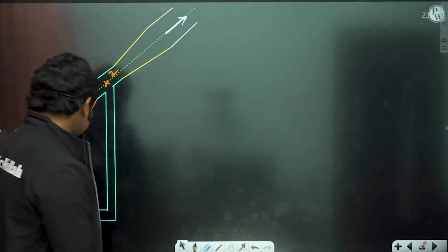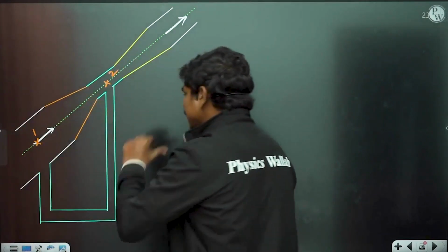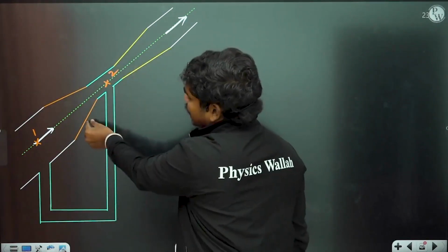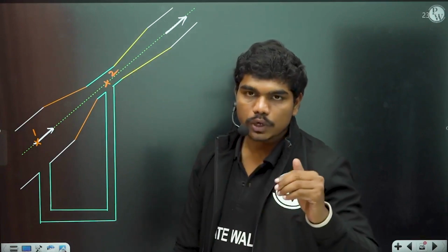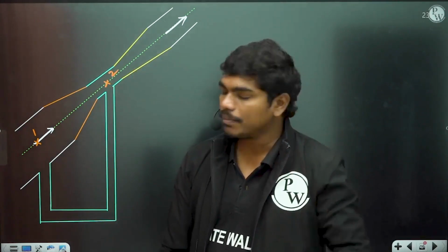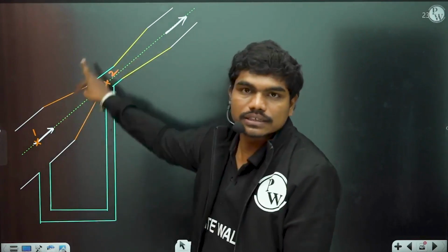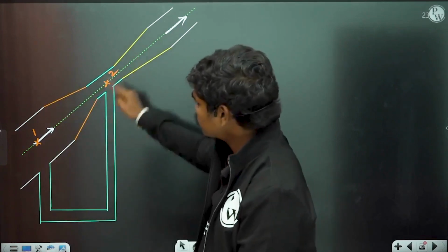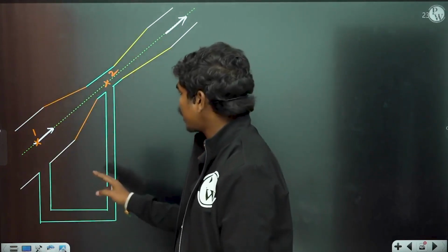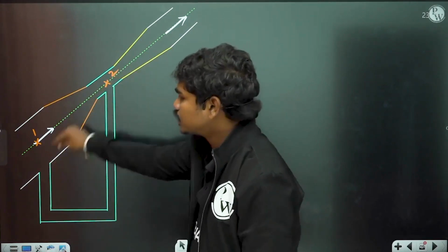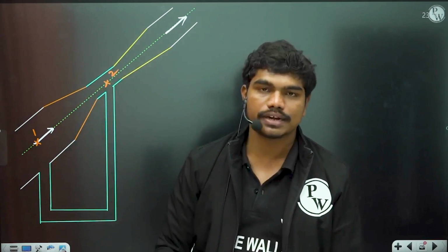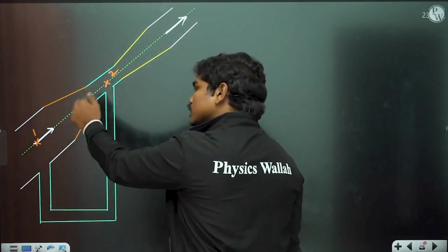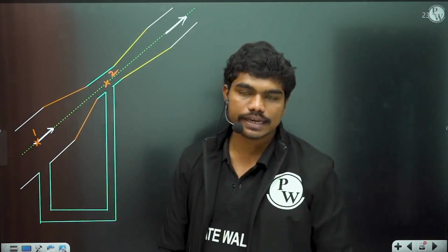Okay, now you have connected this manometer at one end and also at the other. Now they'll ask you why you have connected the manometer like this. Why not connect this point at this location or maybe at this location? Because if you want to have a uniform pressure, the velocity should be uniform. If you connect this limb here or here, these ends are subjected to some acceleration of the fluid, so pressure fluctuations will be very high in these two locations. That's why we do not connect any limb of the manometer between these two locations. We connect manometer limbs only at locations of uniform flow diameter or uniform flow area. Otherwise, if you connect this limb here, there is some fluid acceleration, so definitely some pressure variation takes place, and that should not happen.